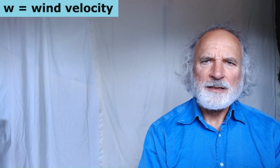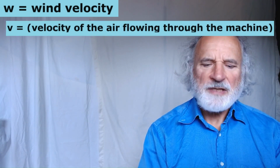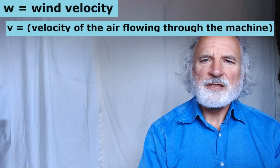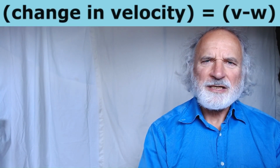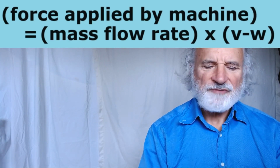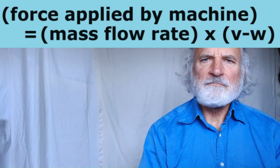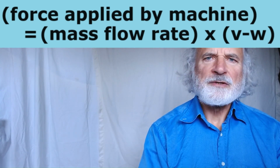Upwind of the machine, the velocity of the air mass is equal to the wind velocity, W. I have defined the velocity of the air flowing through the machine to be equal to V. The change in velocity is V minus W. Therefore, the force applied by the machine on the air mass is equal to the mass flow rate multiplied by V minus W. It is in the opposite direction of the wind.